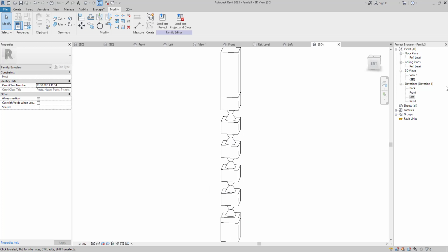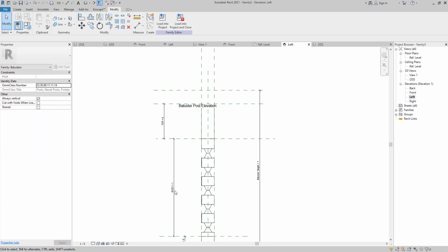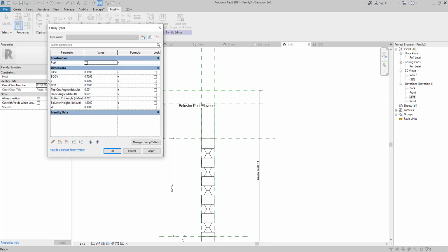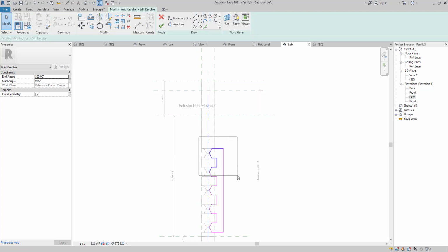It looks fantastic. We will go back and, for example, change our body size parameter. We can come here, body, for example, will be 80 or 90 centimeter, apply. According to that, you also need to change your revolve, because it was made for 70. So I'm just going here, pick this line, copy, and I also need to add this one too.